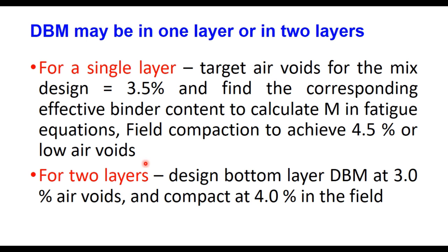When it is laid in two layers, the bottom layer DBM will have 3% air voids, and that should be compacted at 4% air voids in the field.